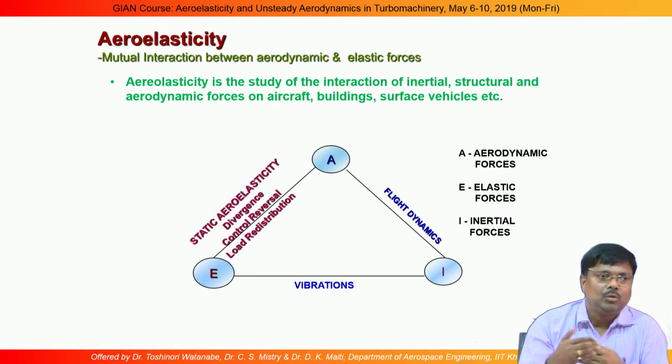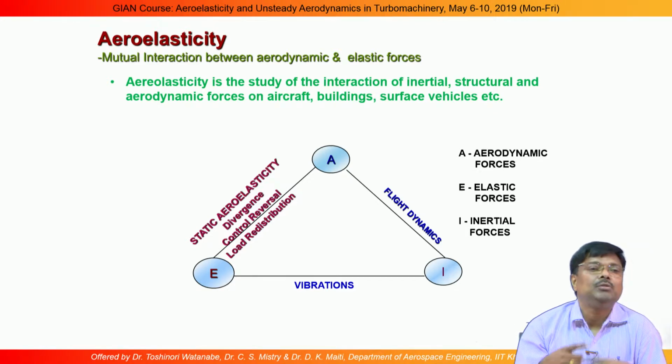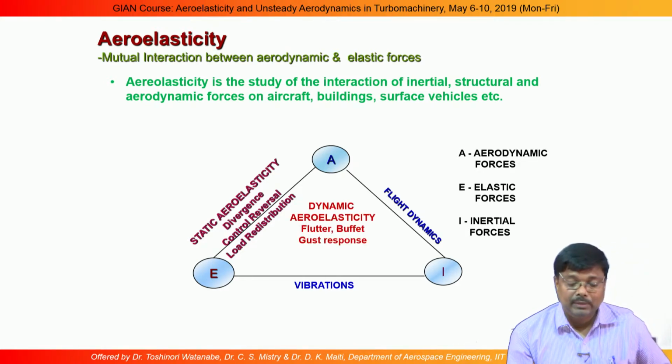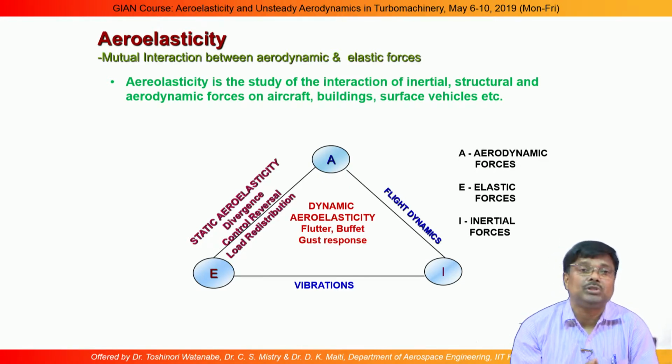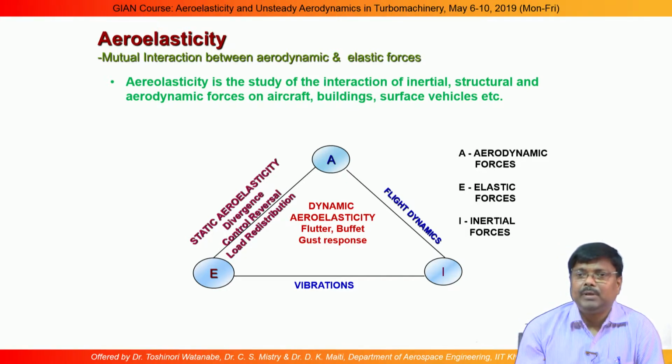Once we go for that, there will be a lift distribution, but when I consider the flexibility of the structure, the load will be redistributed. That is the actual load acting on the structure, and that is important for our calculation. Then, when the aerodynamic force, elastic force and inertia force act together, we can have dynamic aeroelasticity. There are typical phenomena of dynamic aeroelasticity.